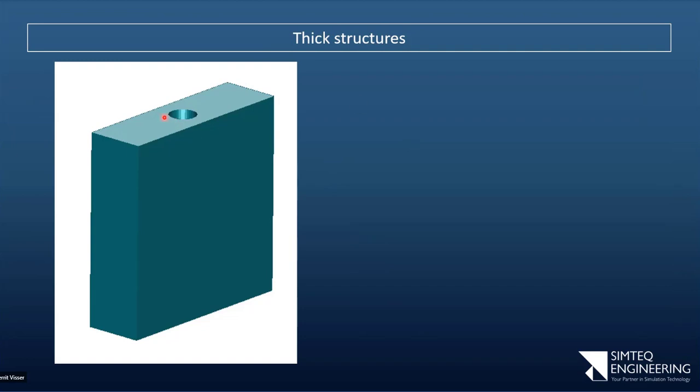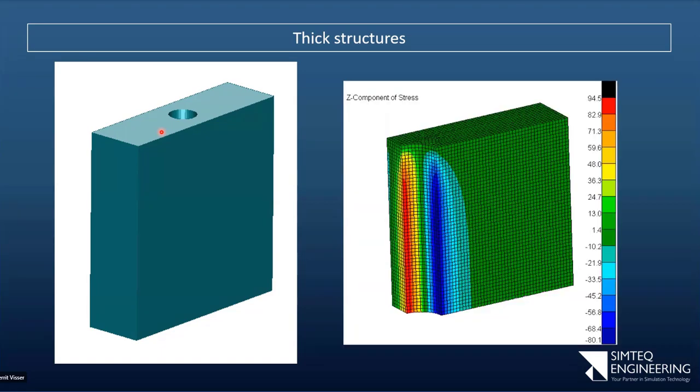So this is that same model that I've got pretty thick, and I'm applying in this direction, exactly like that initial model, a load in this direction. I've modeled this one so that there's 0 stress concentration. It's a perfect tensile pressure applied to those and just enough constraints to get this model stable. So there's the results for a section that is an eighth of a section. So I've got a quarter over there and it stops at the halfway mark. So this bottom section over there is the halfway mark.